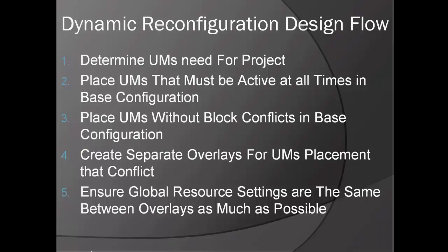Now that you have a basic understanding of dynamic reconfiguration, what it is, why it is used, and how to configure PSoC Designer for dynamic reconfiguration, let's take a look at the design flow when creating a project with dynamic reconfiguration. The first step is to determine the required functionality of the project. With this, determine which user modules will be used to accomplish this functionality. Next, determine which user modules need to be enabled at all times. Place these user modules in the base configuration.